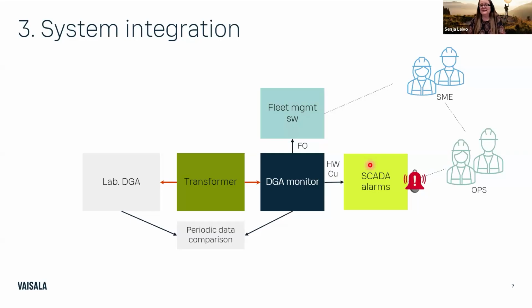An important part here is the people, because monitoring itself doesn't fix anything. It's nice, but the monitors only raise the flag that something is ongoing; they don't tell you what to do or when to do it. So when you plan to start using online monitoring, it's just as important to decide what your process is if there is a gas alarm.